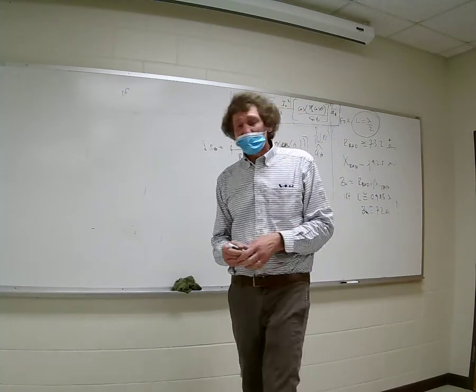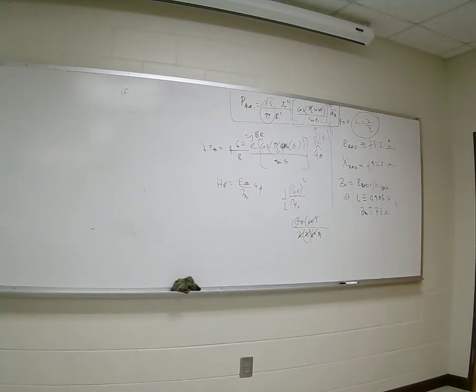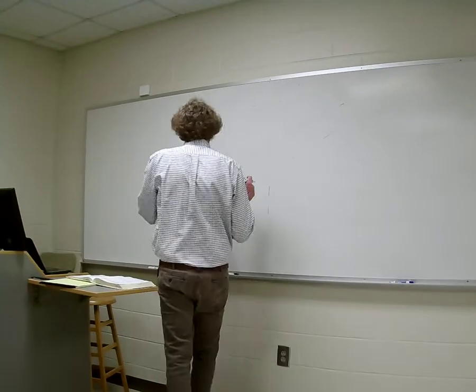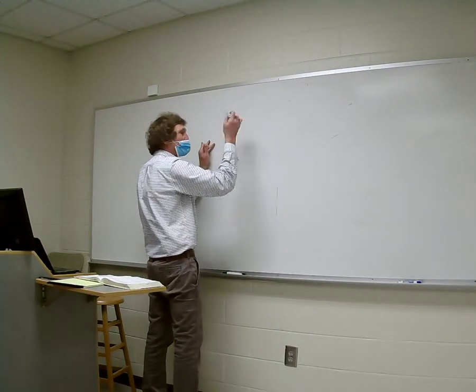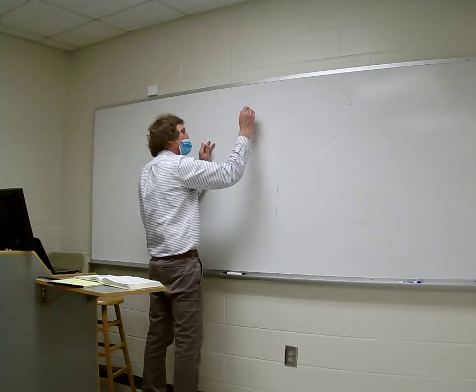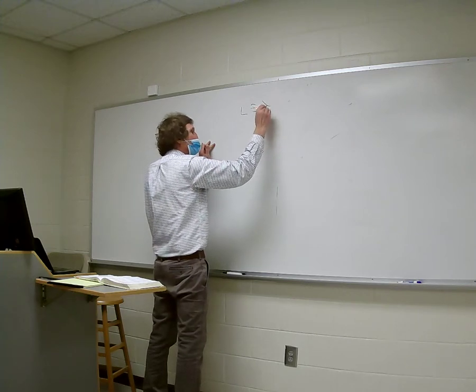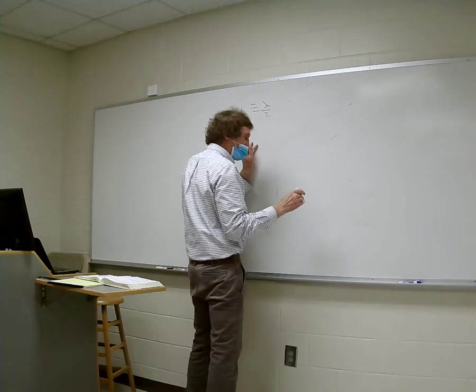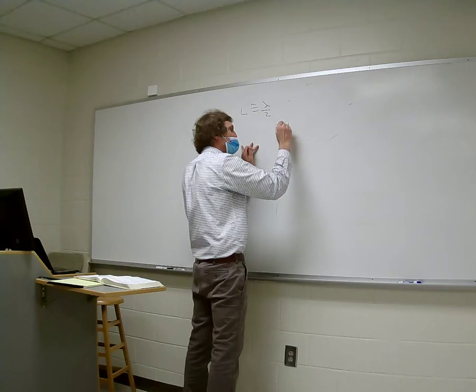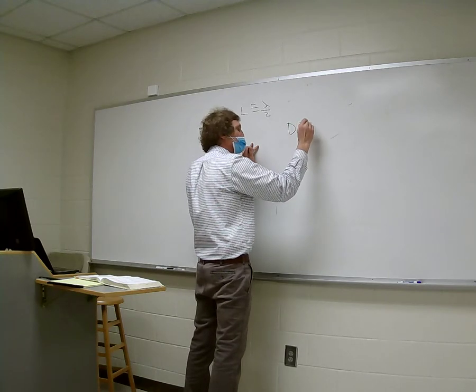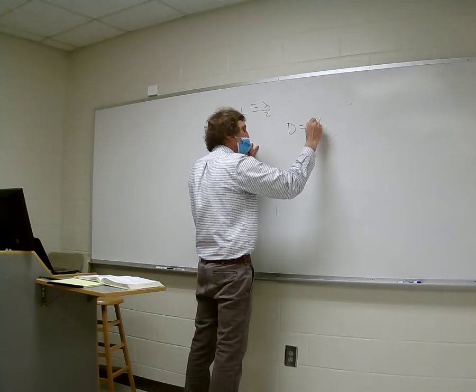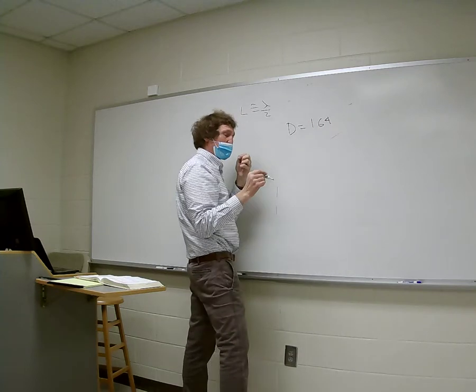Well, for a half-wave dipole, when you go about calculating this, put this down. It's different for arbitrarily long, but worry about the half-wave. When your length is about lambda over 2, or half wavelength, then the actual directivity D is equal to some D max, which is 1.64. That's about always the same.